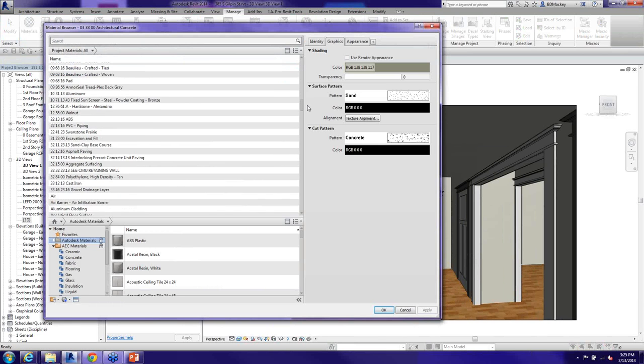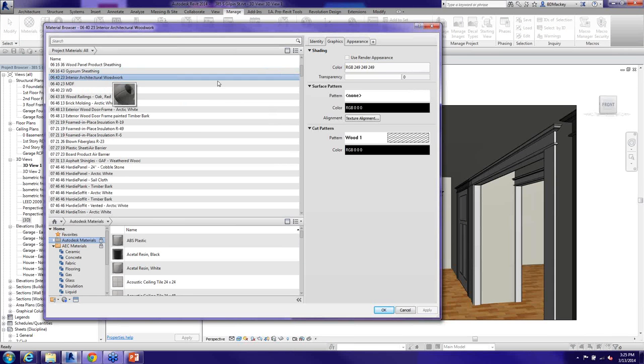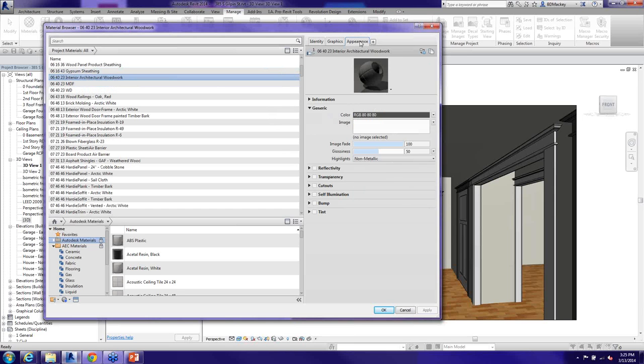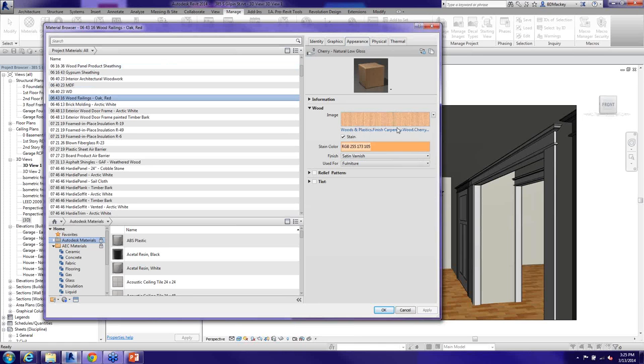But when you go to your material objects here and you start looking at them, one of the things to really start looking into is what the rendering is going to be doing. You can set up shading here, but the big thing you want to do is go to the Appearance library. This Appearance tab is really where you say this is the render material I'm going to be using. Depending on what type of asset you have for the rendering, it can start using different options.